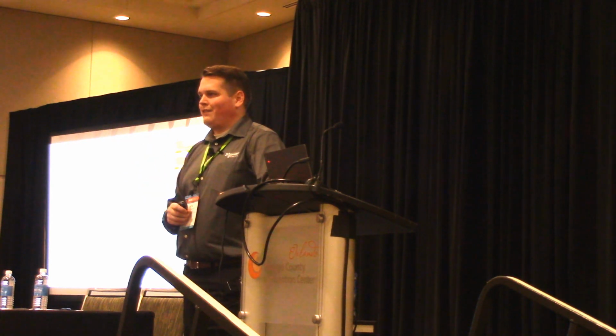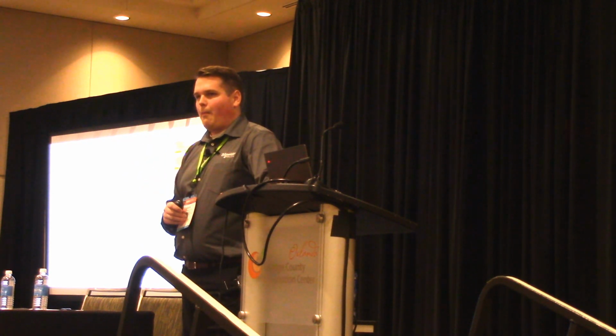Hopefully save you a little bit of time and not have someone have to go out there as often, because you can record that, pull the data, as often as you'd like, and be good to go. But you can do that with chill water or hot water either one. Yeah, so commonly we'll take like a pressure, temperature, and flow input, and use that to calculate the BTUs. Right. Yeah, exactly. Yeah, mass flow. You could still do it based on the condensate return, but a few different ways to do things.